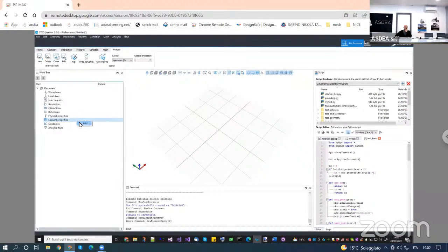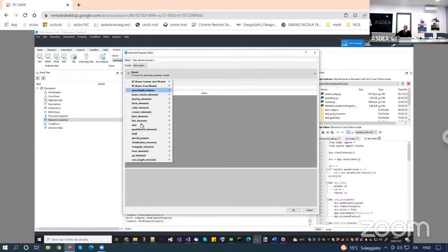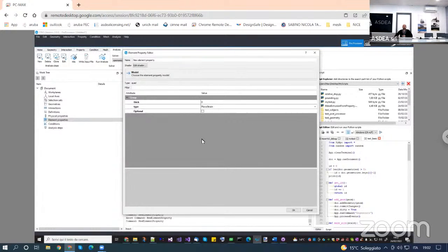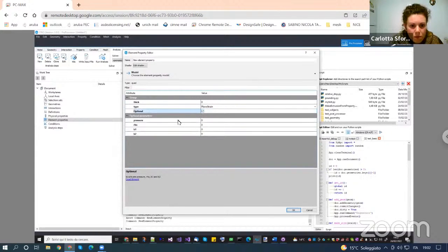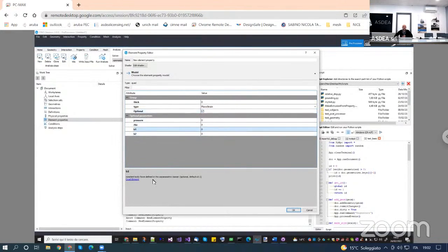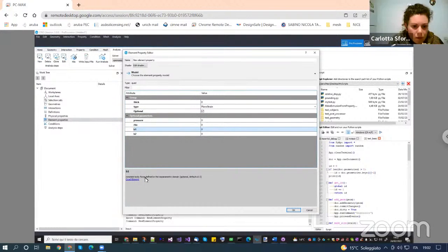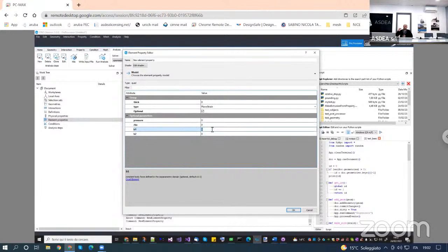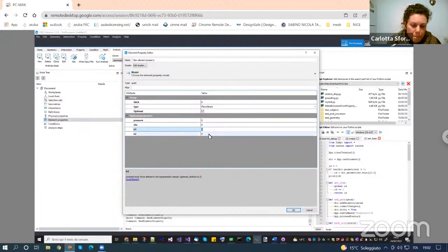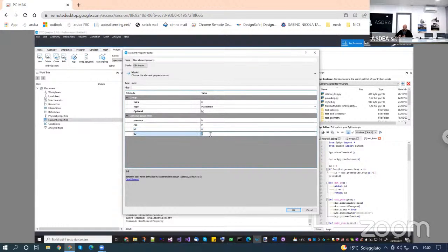So if you use standard elements either in 2D or 3D, for example, let's go into the analysis, quadrilateral elements, quad. If you want to assign the self-weight here, you can click on optional, and then you have B1, B2. As you can see, this one is the constant body force, clearly explained as a body force. In your case, it will be rho times g, so you can put minus whatever it is here.